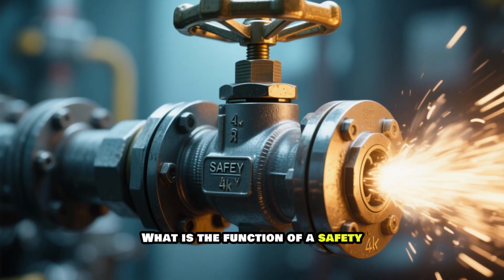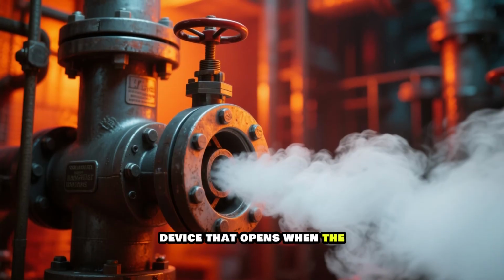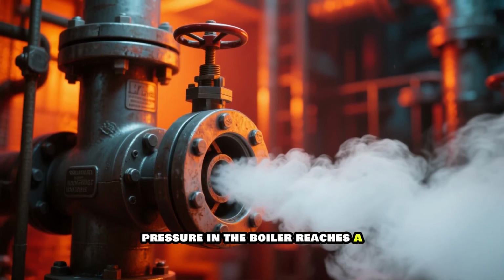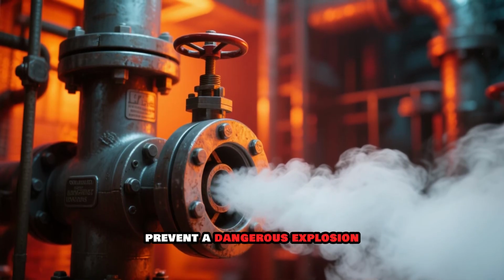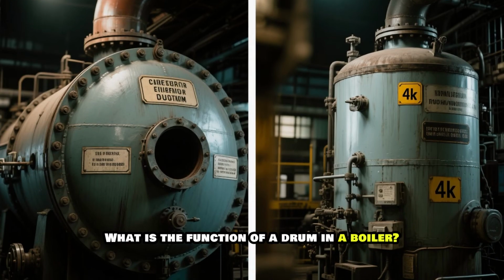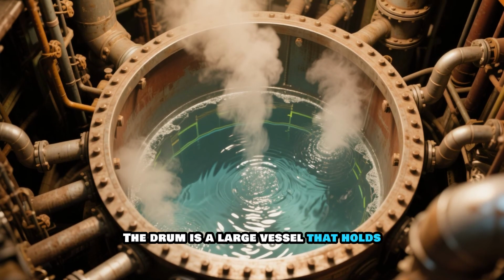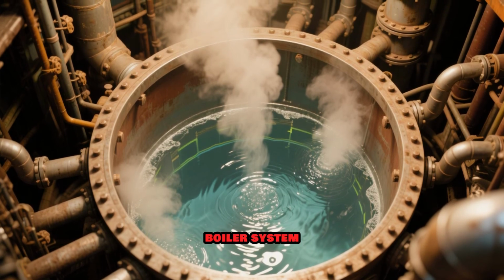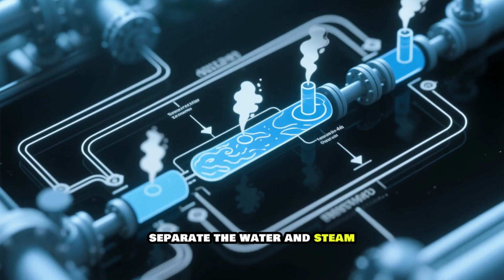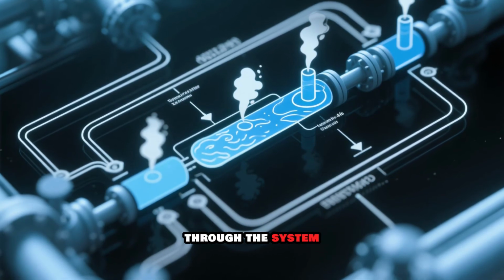What is the function of a safety valve in a boiler? A safety valve is a device that opens when the pressure in the boiler reaches a predetermined level, releasing the pressure to prevent a dangerous explosion. What is the function of a drum in a boiler? The drum is a large vessel that holds water and steam in the boiler system. It is also used to separate the water and steam, allowing them to flow separately through the system.